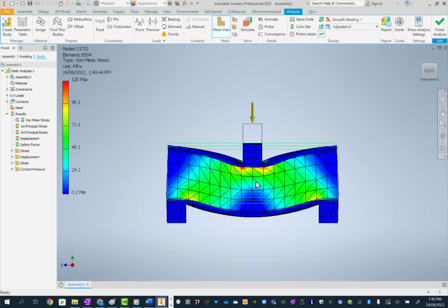As we come down through here, although they're deformed, they're not really forming these parallelograms. So the corners are almost square. So the shear through here would be a bit lower. And then the shear is getting higher again up through here. And that's really what your shear force diagram is telling you about. When shear is low, your shear force diagram will be near zero. When the shear is high, your shear force diagram will have a higher value.